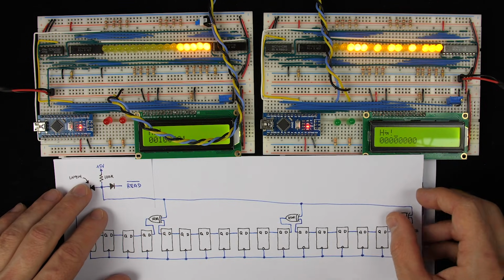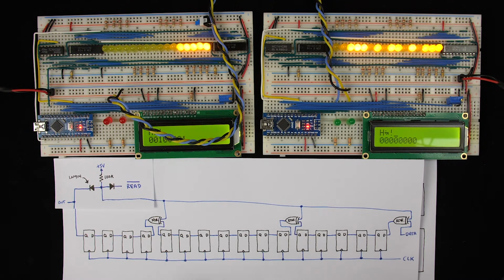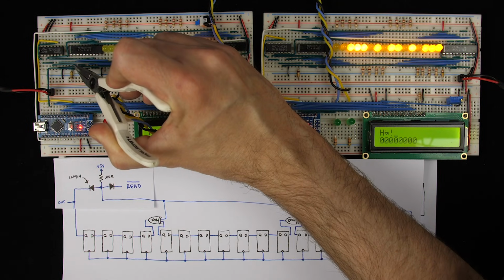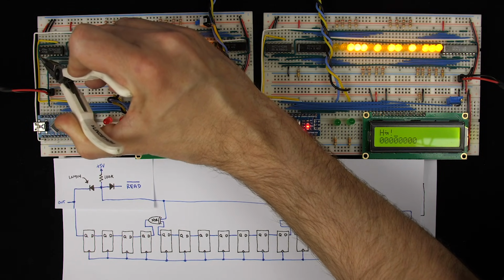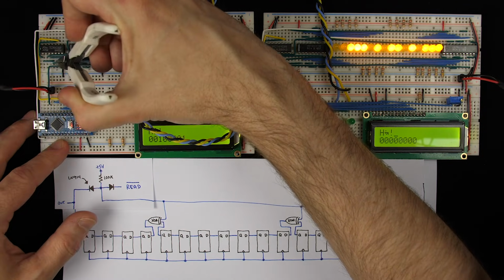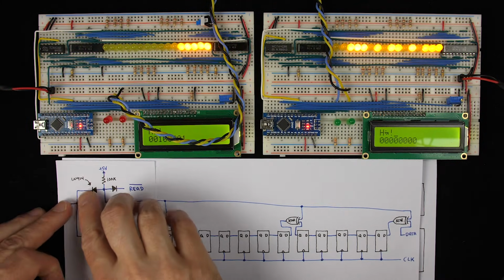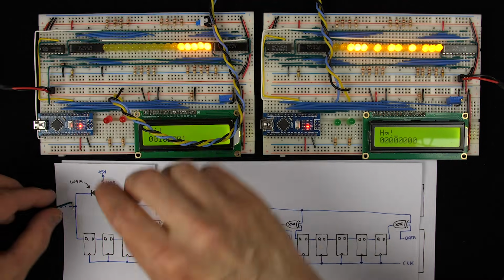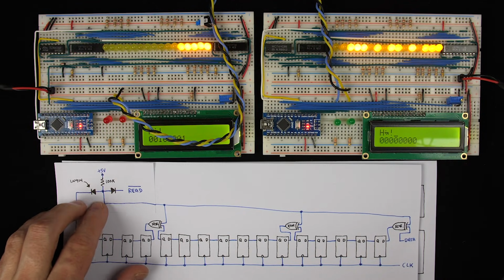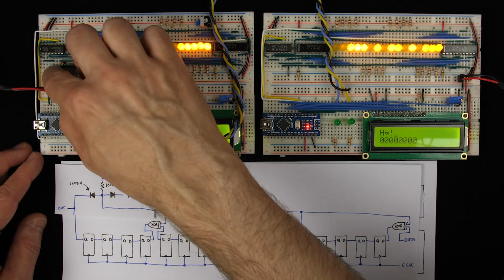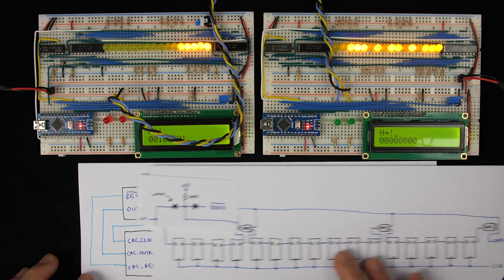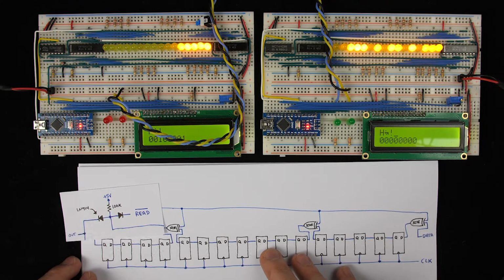So with that out of the way, let's go ahead and build our little diode resistor AND gate thing. We're replacing this wire that goes from the output of the last flip-flop around to all of these XOR gates. So that's this wire right here. We'll pull it halfway out, and I'll replace that wire with this first diode on the left. So that comes out and this diode goes in. Then this side of the diode we want to pull to 5 volts through a 100K resistor. So there's a resistor. And then we have another diode that goes to the read signal, which we're going to connect around to the Arduino somewhere.